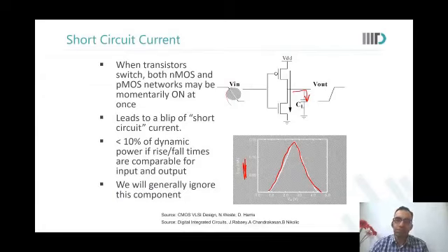Rajneesh? So, sir, when Vout is charging from VDD via the PMOS, this short circuit glitch will occur. And similarly, when CL is discharging via the NMOS below, then this short circuit glitch will occur. So this is the same thing as the glitch in the activity factor, with activity factor 1.